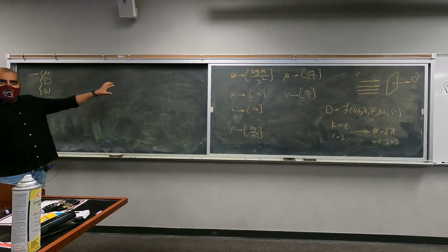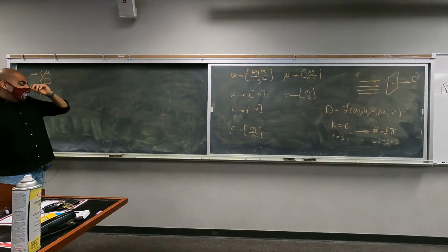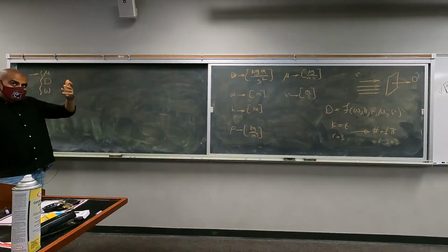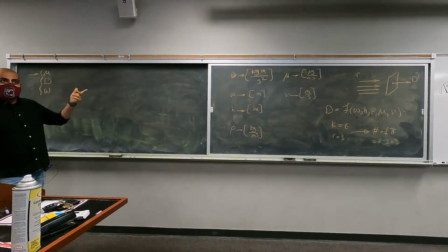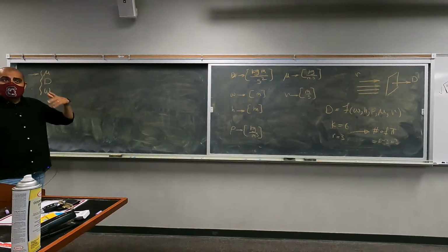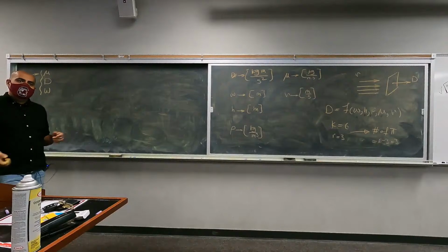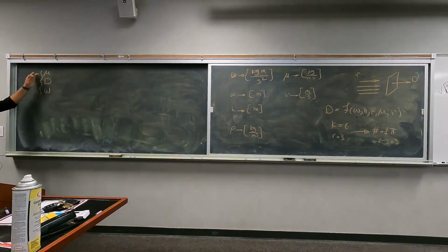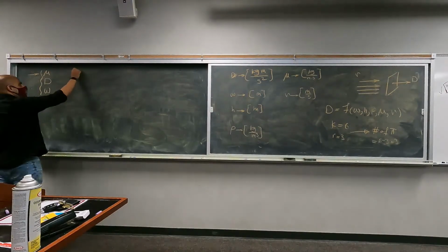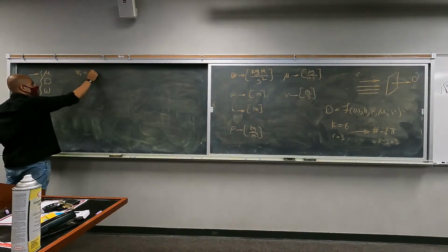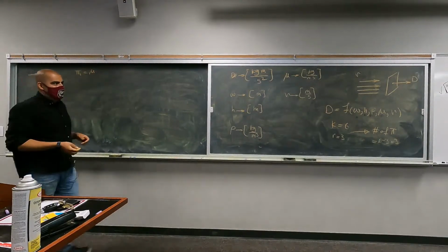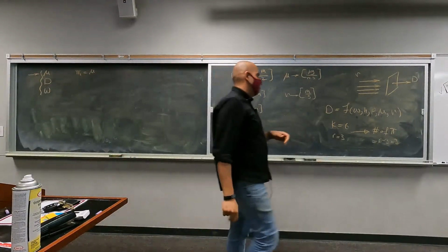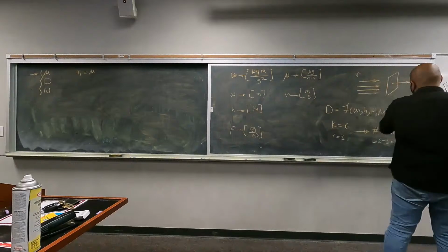If you come up with a nonsensical dimension, by nonsensical I mean something that is not common, the other 2 pi terms are going to be uncommon as well. If you come up with a Reynolds number, the other 2 will be common dimensionless parameters as well. Okay, so I'm going to choose these 3. And what is the next step? Your pi 1 has to be equal to mu multiplied by the other parameters that are there: your height, density, and velocity.